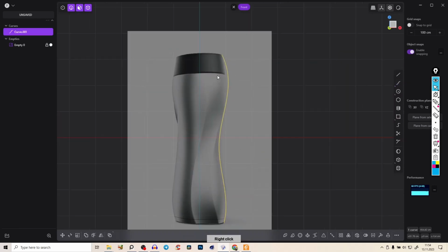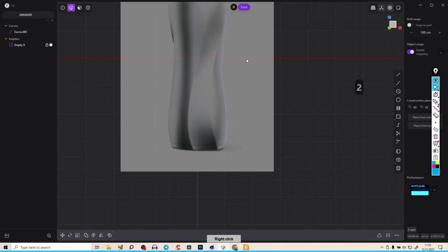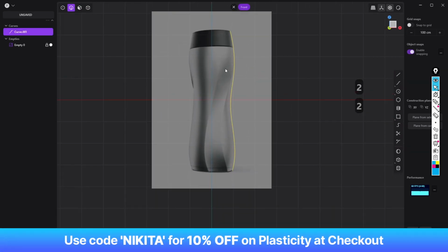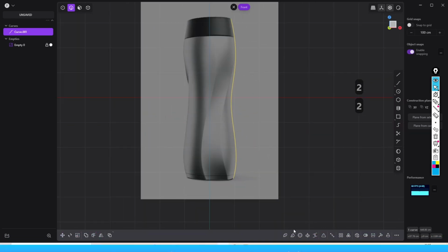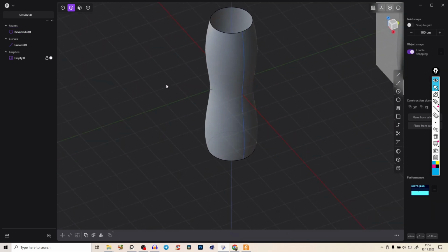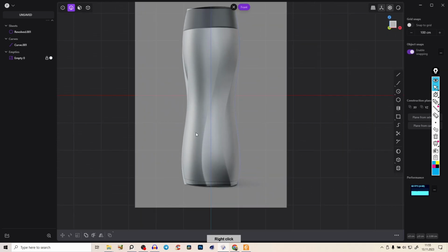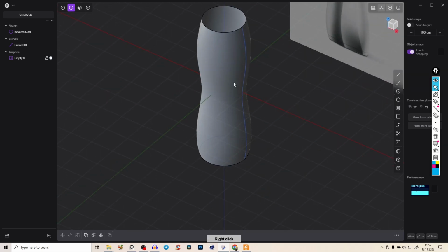So just create here a curve, press 1 and adjust the curves. So yeah, for this tutorial it's fine. And you see we have just one curve. And this is what we want. So now we press revolve and snap it to the Z-axis and just drag it up. And voila, we have here our main form. It doesn't look as our bottle, but hold on.